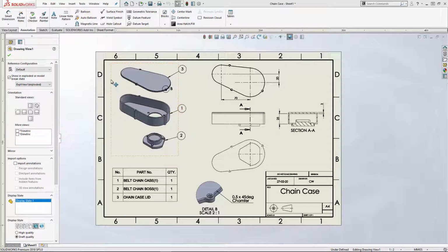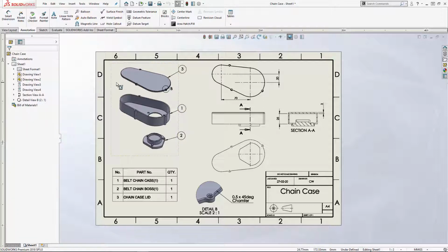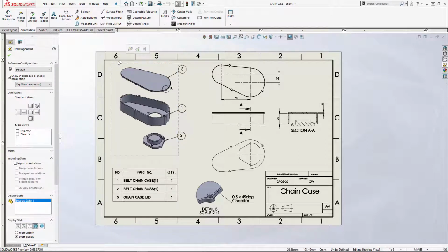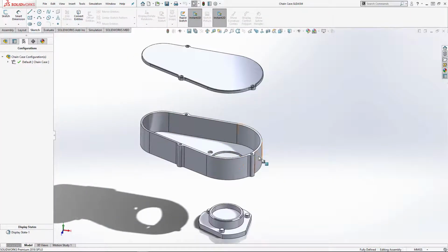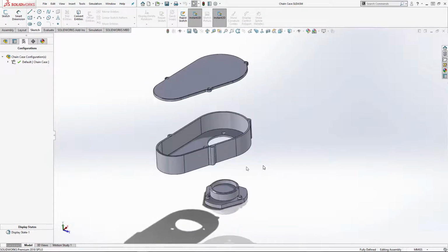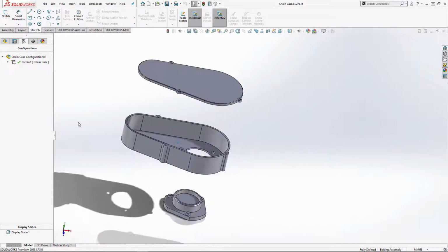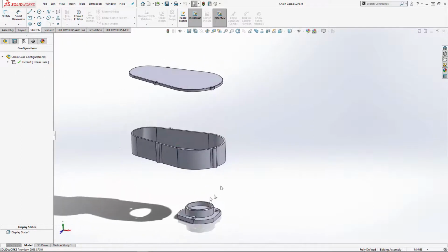So the first thing that we're going to do is create a fresh drawing. We're going to use this drawing as our guide, so we'll keep this open in the background. So this might be quite useful. One of the first things I'm doing, I'm clicking on an assembly view in a drawing, and this icon that pops up there allows me to open the assembly that view is showing. So that works for parts as well, but we want to create a new drawing of this assembly.